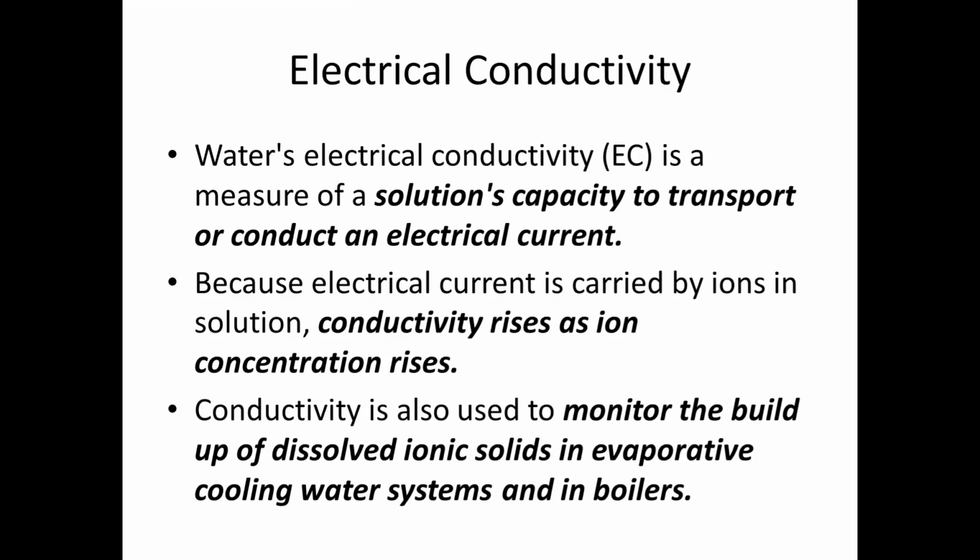also conduct electricity. So because electrical current is carried by ions in solution, conductivity rises as ion concentration rises. I want you to take note of this. Conductivity rises as ion concentration rises. When our ions or solids in our water increase, it conducts electricity more. They are actually in direct proportion. The higher the solids or ions, the higher our conductivity.